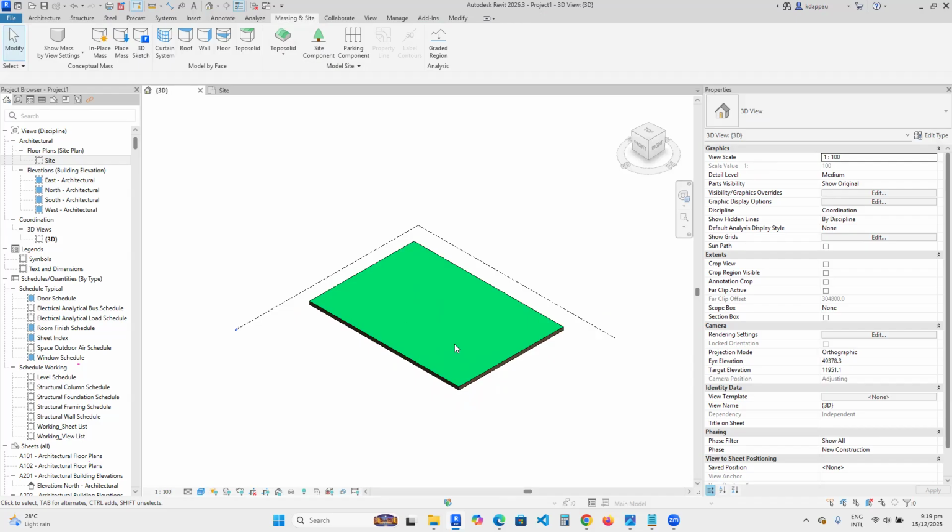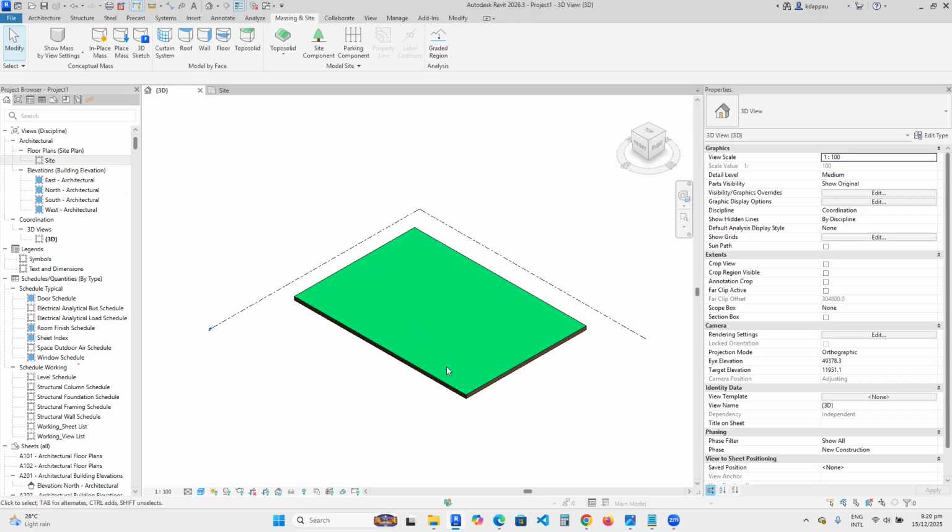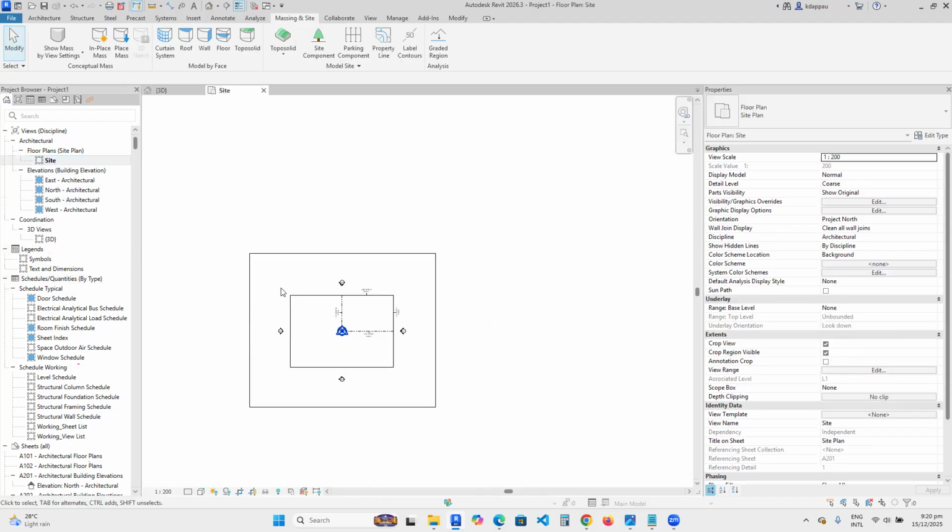Do you appreciate what I'm saying? Yes, I'm following. So the building project you've done already, you've only done the building. You've not done the what? The site. You understand? But now that there's a site, I can bring in a building here and then place my building here. So I can go to, for instance, the site plan again, go to Revit links.